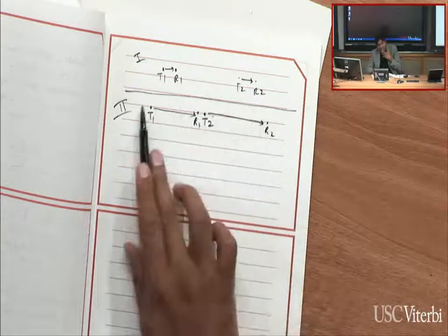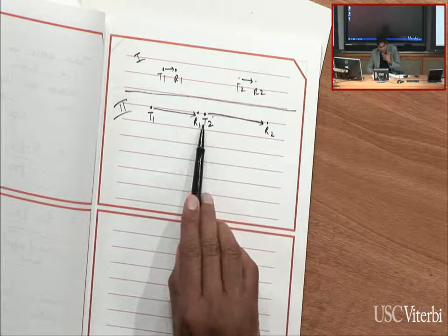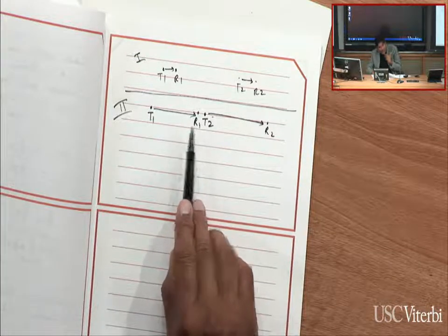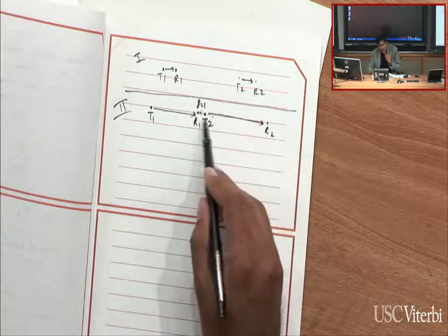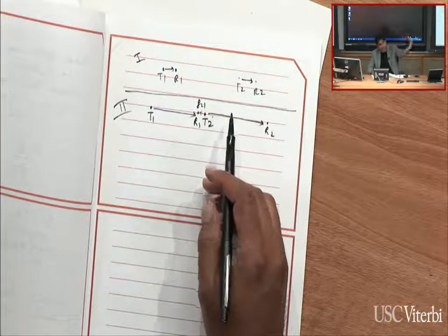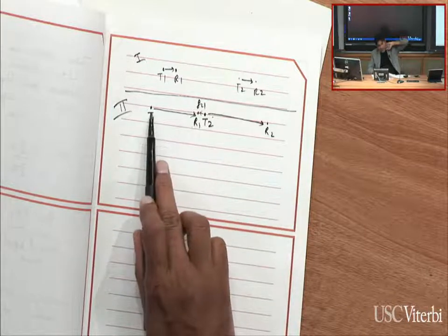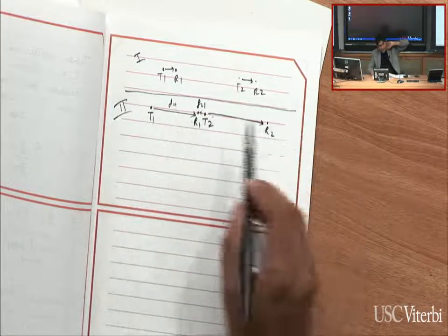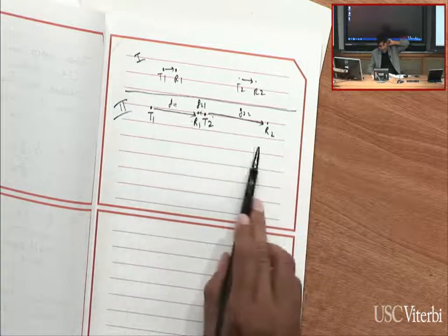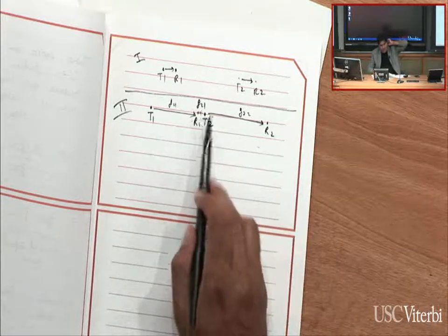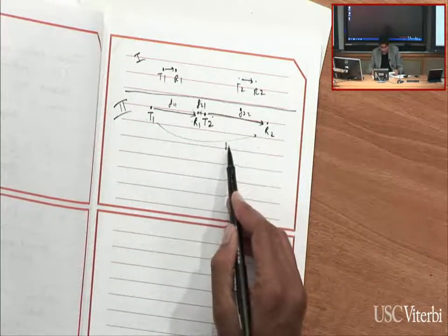And in this scenario, although it's not trivially obvious, you can kind of see what's happening. Now, the cross interference from T2 to R1, this term, G21, might be really very high. It's not very far from each other, so you get a lot of interference. On the other hand, the forward gain term G11 is very low. The forward gain term G22 is kind of low. And the other cross term doesn't really matter. It is low, but it doesn't matter so much as this term being really high. Of course it depends on the actual numbers, even of the G12 term.